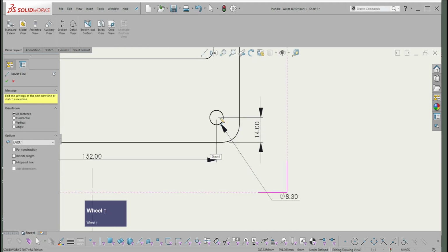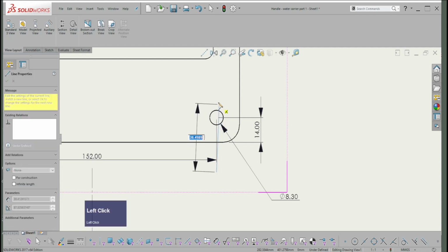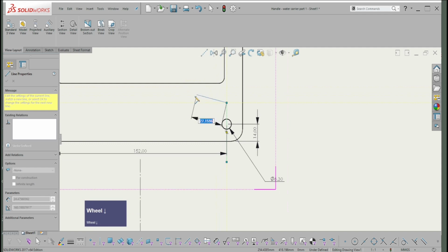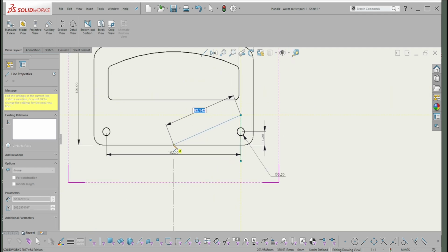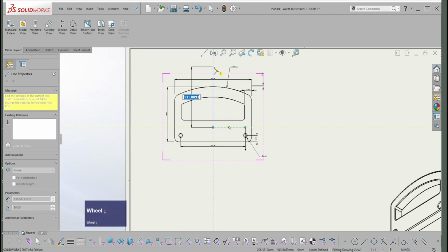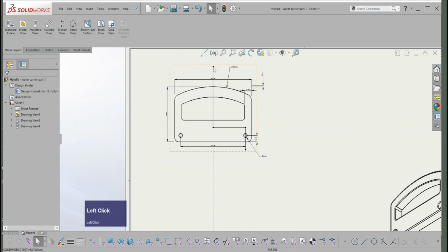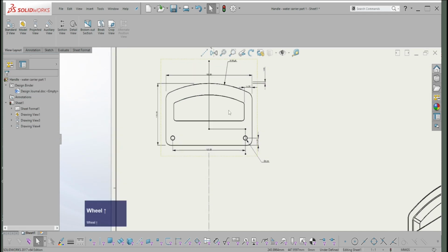from the outset, and I'm going to just get my mouse to pick up the center of the circle, drag it out so that you've got that lined up, and then make sure that you drag the line well beyond the boss, because remember the boss actually is slightly larger. Let's go left to the middle, so let's just pick up on this midpoint and then go up way past. So now I've got a jogged line, a sort of an L shape, or something like that.